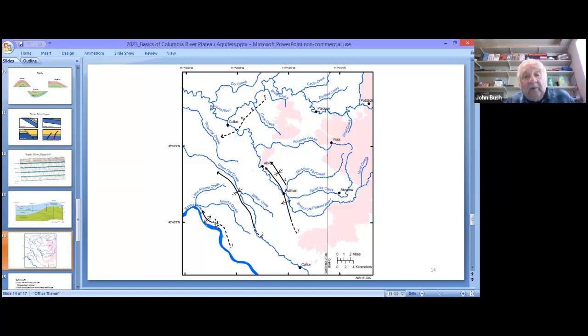There's documentation that the water is moving away from that anticline down into the syncline area. It's not moving out and coming out of exposed aquifer rocks that are in the same sequence as Pullman. There's not any water coming, or very little water coming out of those springs on those slopes of the Snake River. Water is flowing, in this case, down into the Union Flat Creek area, away from the Snake River.